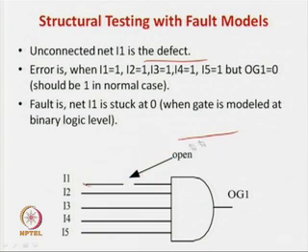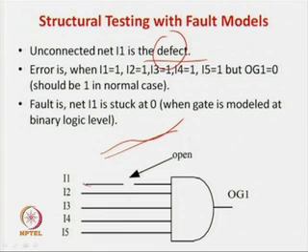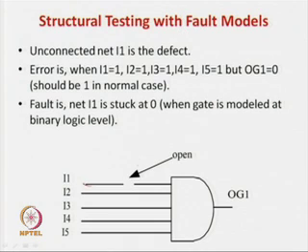So, there can be hundreds or thousands of defects. For some place maybe the wire is not cut, but has become very thin, so that can be a defect. Or somewhere the line is a bit thick, that can also be a defect. That is very difficult, you cannot do all the testing in the small amount of time given. So, in this case this is a stuck open, this is the defect.